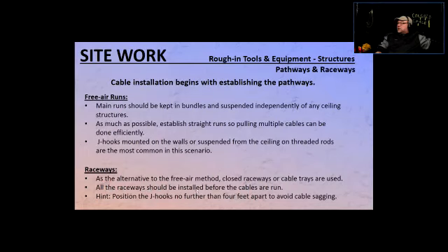All the raceways should be installed before the cables are run. So you're not going to run the cables and mount the raceways at the same time. Very seldom is that the most efficient way. What's the most efficient way? You go on the job site, and according to the survey notes, according to the drawings, and according to the reality, because the reality can change. There could be something that they added on, maybe a different heat pump, and maybe something had to be moved from the plumbing things or heating ducts or whatever, and it's in your way.